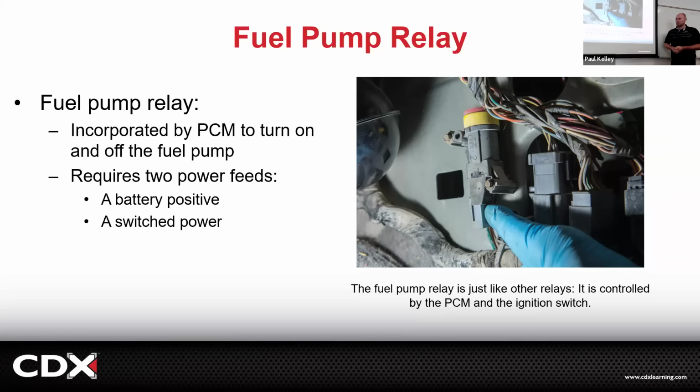So they came up with this thing called an inertia switch. Basically, the inertia switch is a device that, if you get hit hard enough, will trip and kill the fuel pump. So it's kind of crazy. You'd get in an accident, fix all the body damage, and it still wouldn't start. Then they tow it to the shop and it's, yeah, that's got an inertia switch. It's a Crown Vic. Push the inertia switch, click, boom, and that would let the fuel pump fire up.